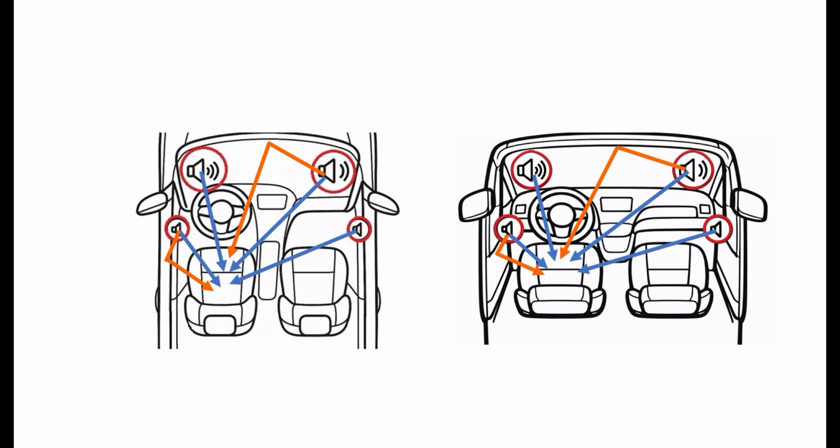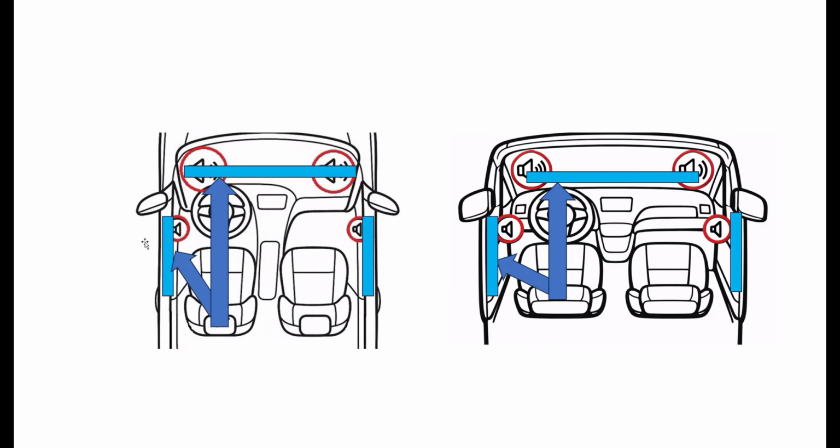So we've talked about the high frequency notes, the tweeters, the mids, and the mid-range, which you can't usually do much about because they're usually in a fixed position. But if you have your sub in an enclosure and it's not permanently mounted in, let's say, a trunk IB baffle or something like that, then this might help. So if you've got the sound bouncing around in the cabin and off the windows and all this type of thing, and you want to do something about the sound of the bass, there's a couple of things you can do.